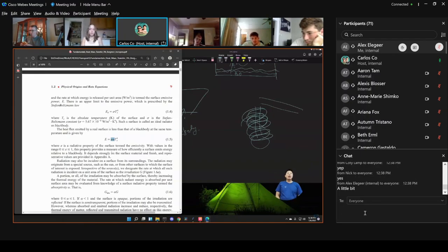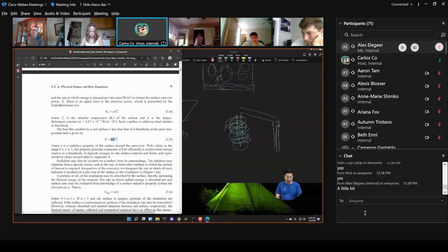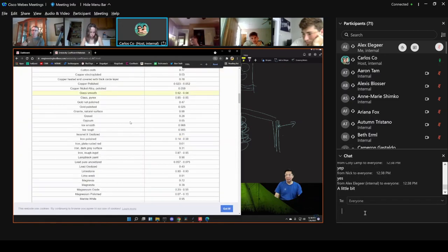And so what happens is that, if you don't have the aluminum foil there, you have glass. Well, this glass gets hot, so the glass is going to radiate heat. If you look at the emissivity of glass, Pyrex glass, the emissivity is about 0.9. Even though Pyrex glass looks transparent, it doesn't look black at all, it gets pretty close to a black body.